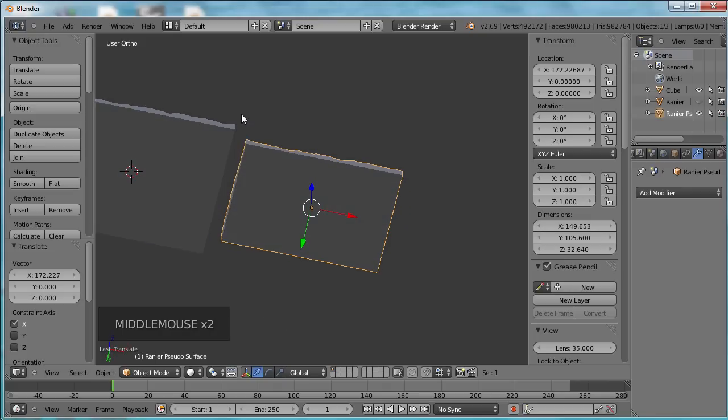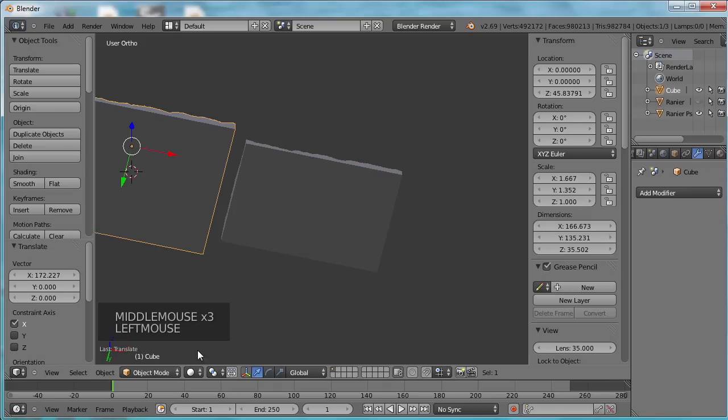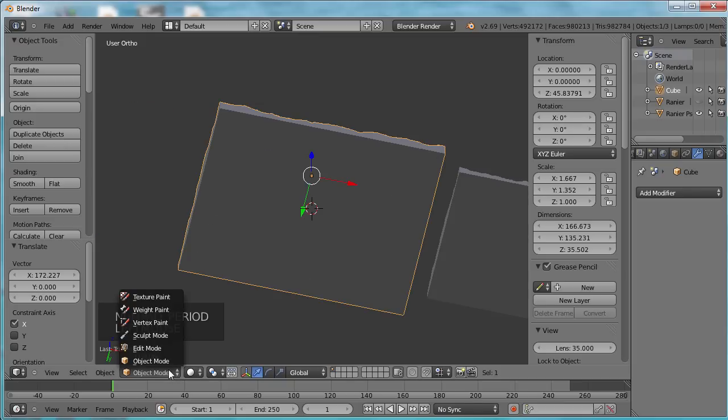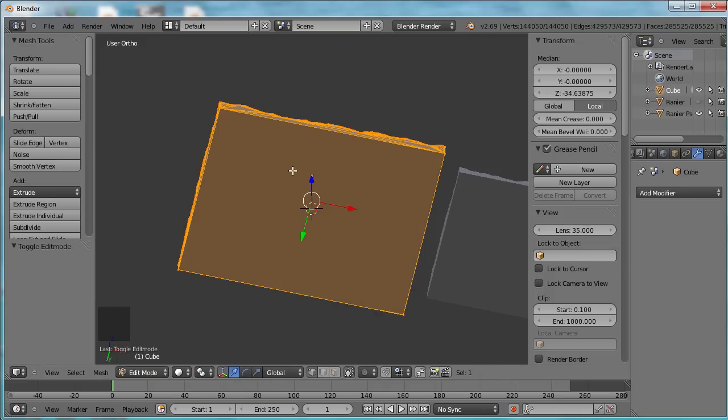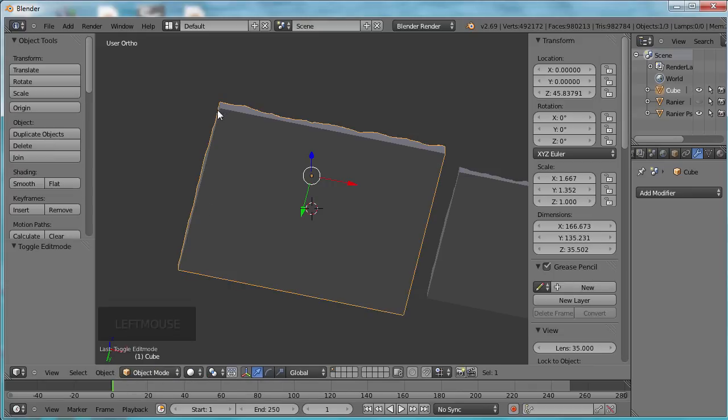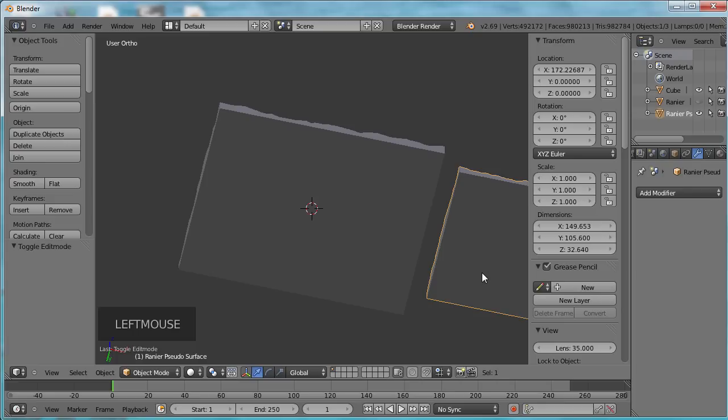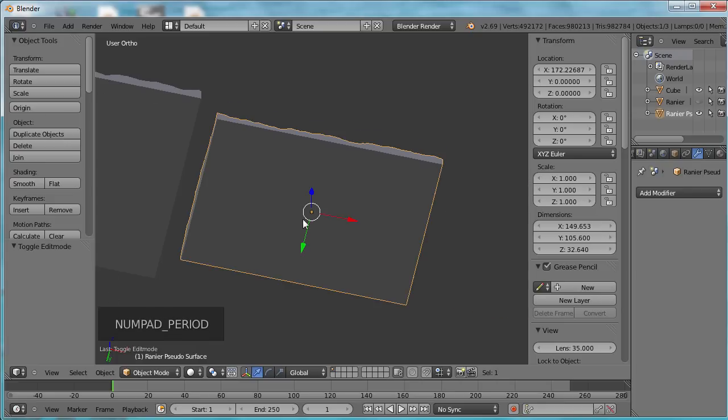So if we look at the bottom side of it, and we're going to go into edit mode here, this shows us that we have one square that is our base, basically one polygon. That is the bottom of our model, the one we did in Blender. And that's how it should be. You've got a rectangle. You don't need more than one rectangle or two triangles, depending on if you're using triangles. But that's all the data you really need to define that face.